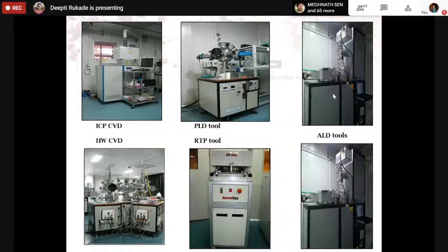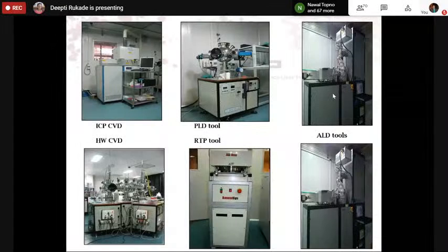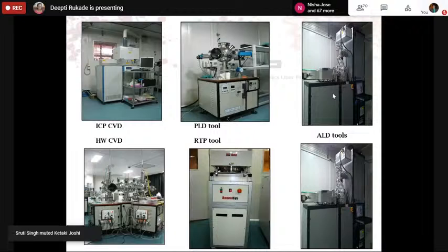In pulsed laser deposition, we have laser pulses that hit the target material. Your target material looks like a tablet, and it is placed in front of the laser beam. The laser beam comes and hits the target, and the target is sputtered. There is also plasma in the system. That sputtered vapor material mixes with the plasma and forms something called a plume. This plume then moves towards the substrate with the applied bias and gets deposited onto the substrate.